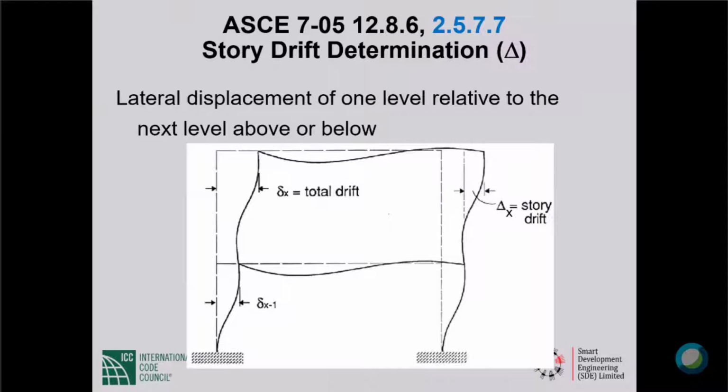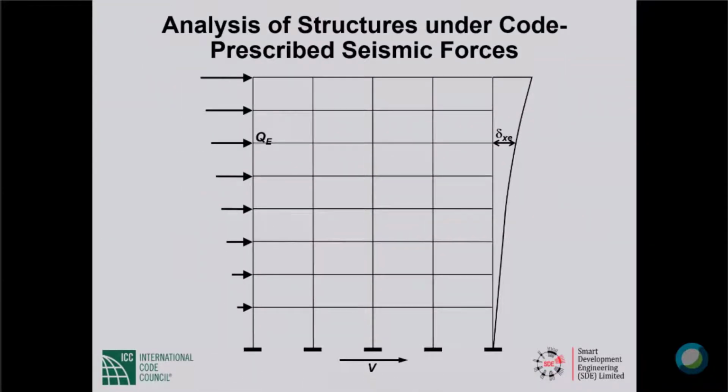If the non-structural components and the equipment supported on the roofs are not damaged, then there is reasonable expectation that the facility will go on functioning during and following an earthquake. There is a control of property damage aspect also to drift check. So this is beyond life safety. I do want to emphasize that. Now, interstory drift is the deflection at the top of a story minus the deflection at the bottom of the same story. That is the first thing. Exactly what deflection we will talk about with this slide.